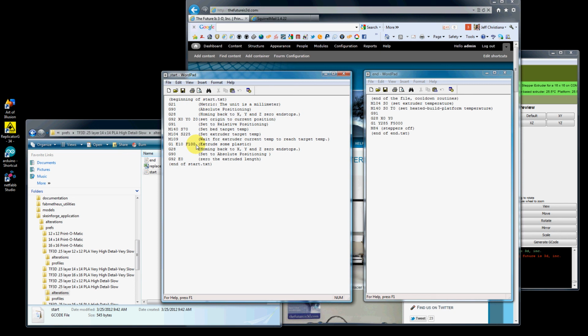You usually print around 70. The motor is capable of going really fast, so you don't want to go too fast. We're doing some experimentation with moving pretty quickly with a lower layer height, so we'll hopefully be releasing our 0.02 layer height here in the next couple months. So, but anyway, I'll have to wrap this video up.